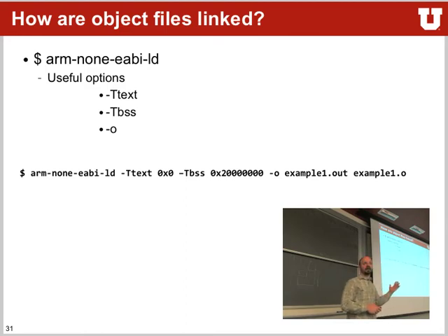So the text section is where all the program code is, so you write that at address 0 and continue from there on. The linker has a really important job here. It takes different object files and places them in the right memory locations inside your architecture. Yes? Does the RAM count up or does it count down? Up.